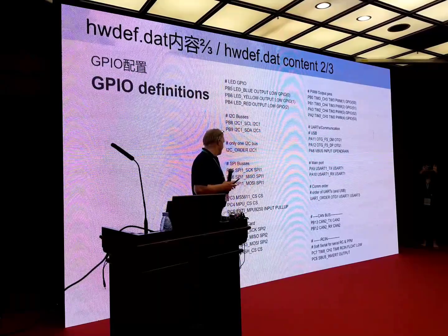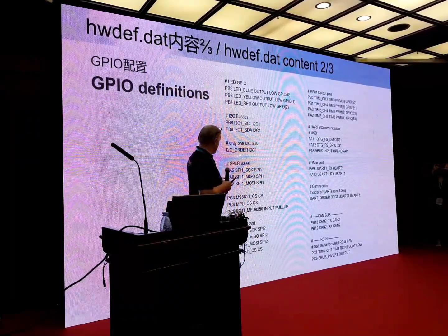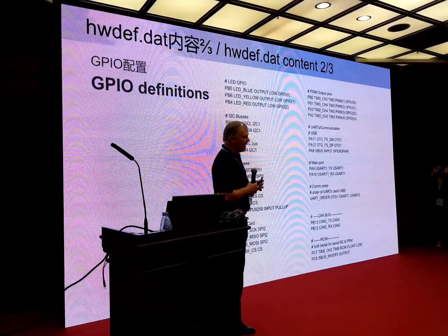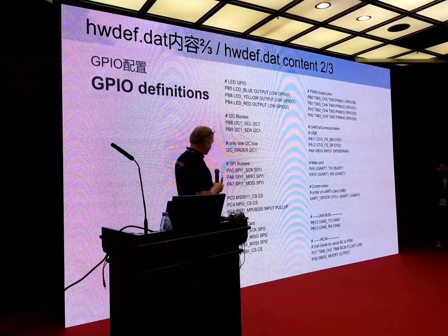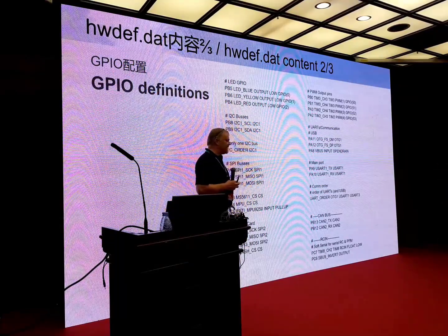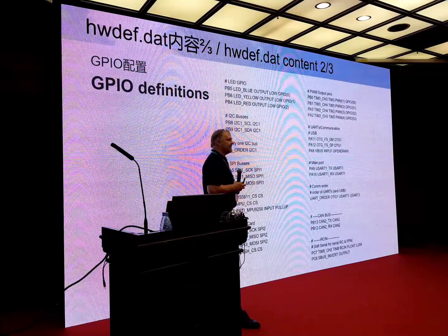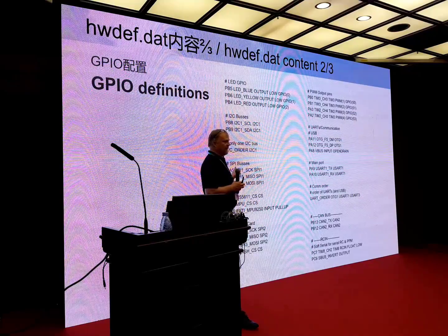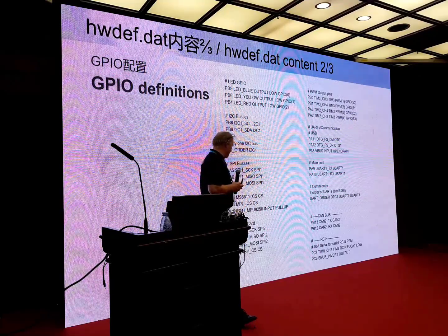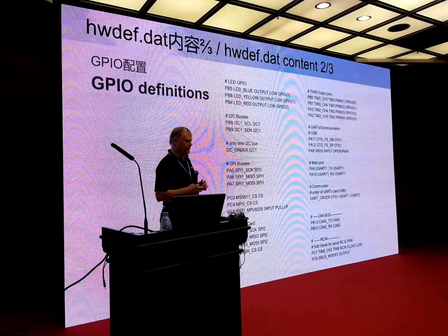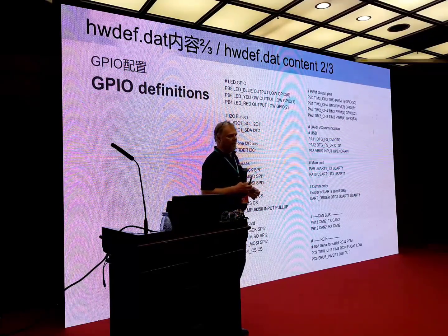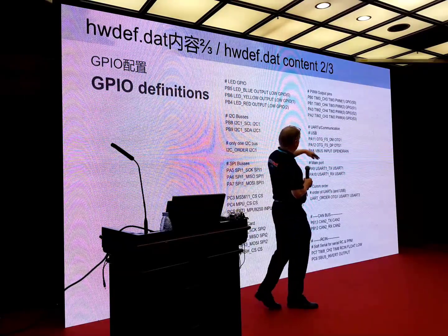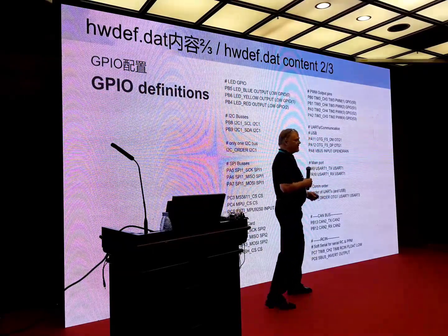SPI, yeah, it looks like this on this board. So PA5, PA6, PA7 are the normal SPI pins. Even though these are related to SPI, it's not that important because they are just normal GPIO. SPI is a special pin in microcontrollers, but the chip select and others are not. So we can basically use whatever available IO pin. Same thing on outputs, USBs and others. It follows the same direction.